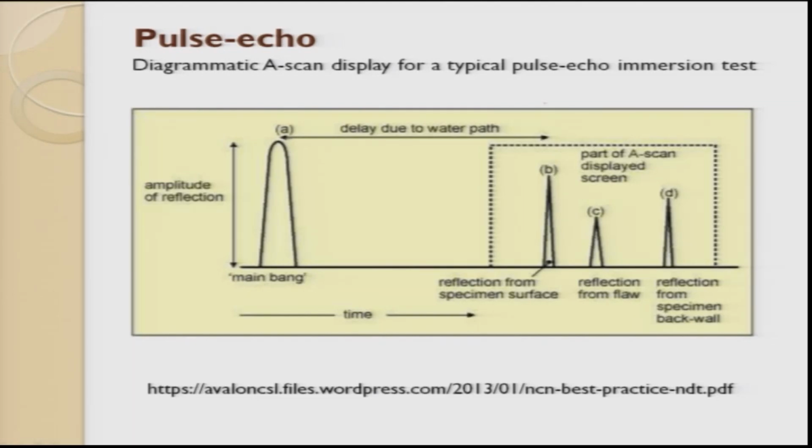What has traveled here is the couplant, which I said we have to use, couplant. It can be viscoelastic, a viscous material, oil or water, and it focuses the sound wave into the specimen. So this is scan A, which I was talking to you about, and you get the signals reflecting from the top surface and the bottom surface. If there is a defect, there is a defect, and here you can also have many small defects like this.